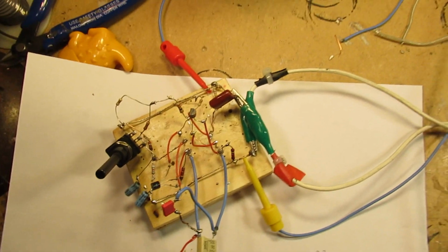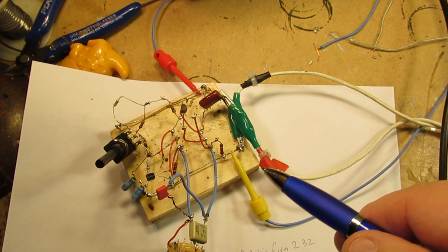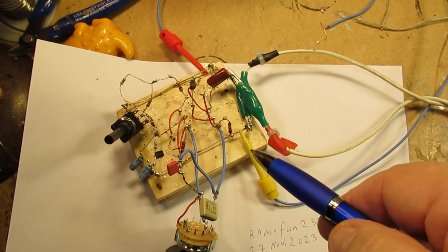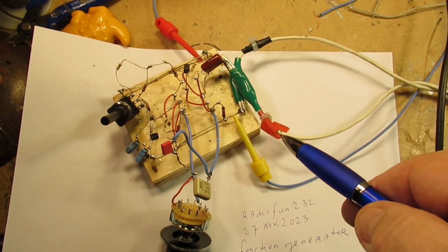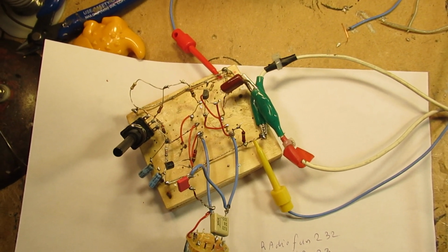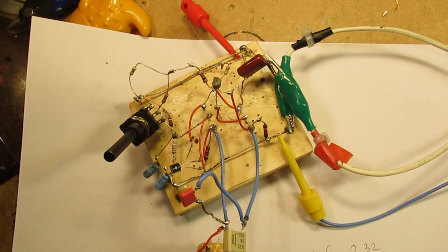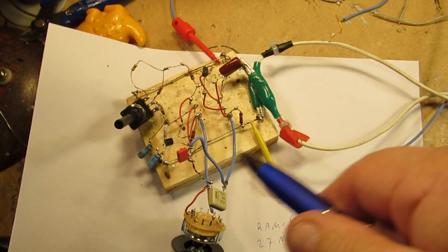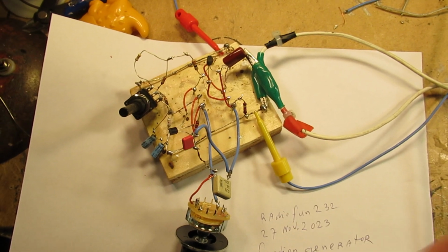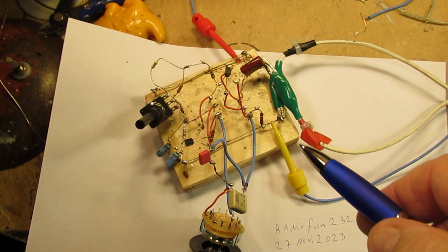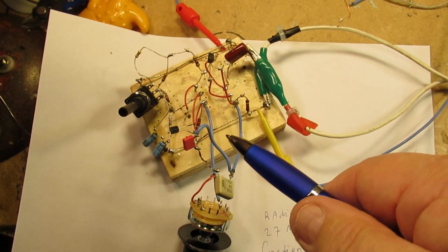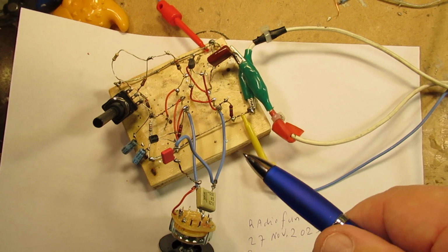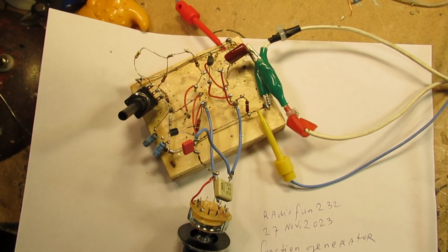That means that for, say, 50 Hertz, when you want to change a square wave into a sine wave, the filter must be made in a certain way and will completely differ from a filter where you want to change a square wave to a sine wave on 20 kilohertz or say 50 kilohertz or 1 megahertz.